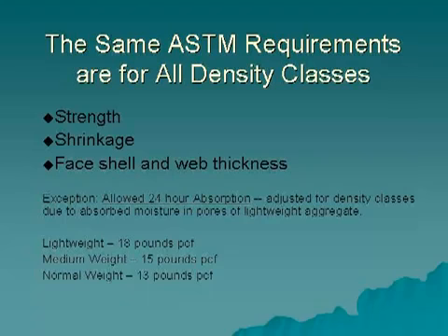Since masonry walls are never intentionally made subject to being totally immersed in water, what is the purpose or the intent of limiting absorption as stated in ASTM C90? In past history, block manufacturers tested their normal weight block for water absorption to control the level of compaction of the concrete mix or the volume of interparticle voids. It was considered, and still is considered, that normal weight concrete should absorb no more than 13 pounds of water per cubic foot of concrete. This still holds true today.